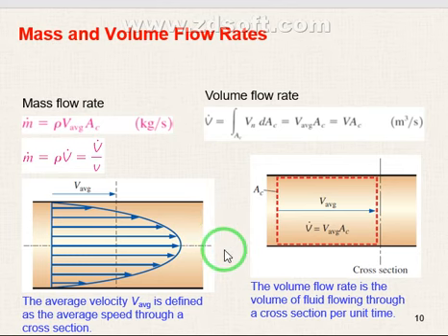Okay. If you remember, when we have a flow inside a pipe, just like a quick revision for you, we don't calculate the flow rate or the velocity based on the maximum velocity in the middle or the minimum velocity by the wall side of the pipe, which approaches zero. No, we use V average, then we calculate the velocity and can do the flow rate. I need you to go back to chapter 2 to understand the concept of flow and remind yourself of it. We did some examples in chapter 2, right? Chapter 1 and chapter 2.